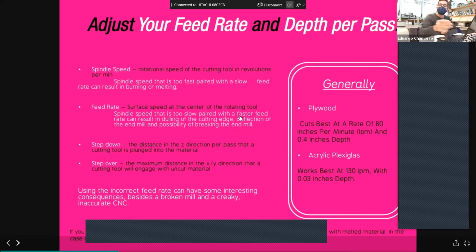For milling wax, in general, you want to run fast on the X and Y, on what is called feed rate or horizontal speed, but you want to go slow on the RPM. So you want to eat a lot of material, but with a slow RPM. So you want to have big chips and almost fill the whole flute of the end mill.